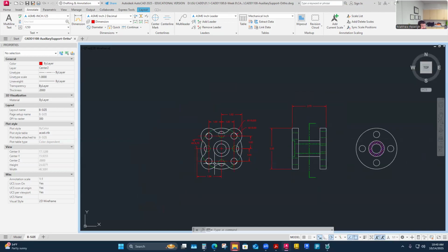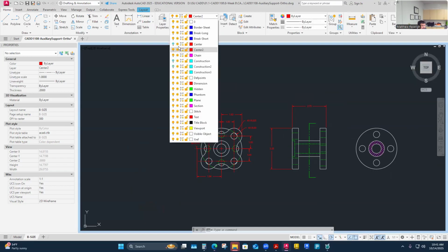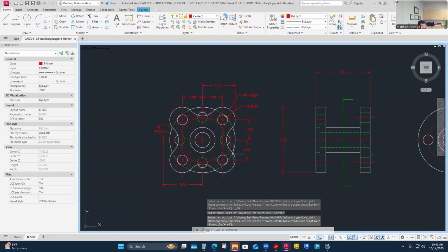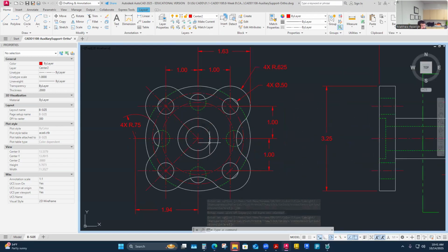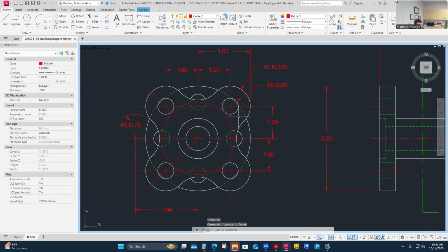Anyway, so what I got to do is clean up. I got to turn on my other. I got to do a bunch of little cleanup work here, just based off how I was demonstrating what I was doing differently. But because I've got this stuff going on here, and I really only want one, probably center layer, everything on. So I'm going to move. I'm going to eliminate this bolt circle that I didn't need in this view anymore.